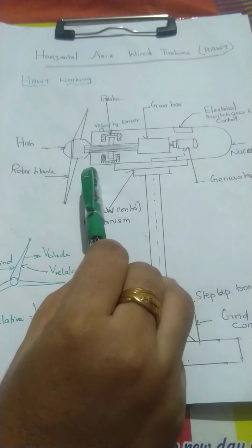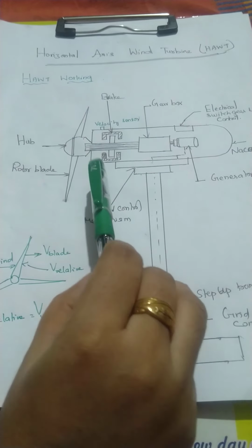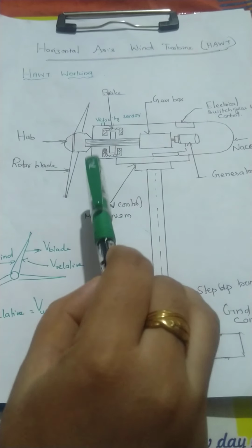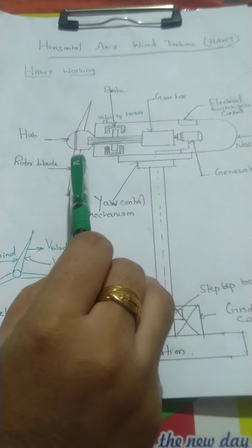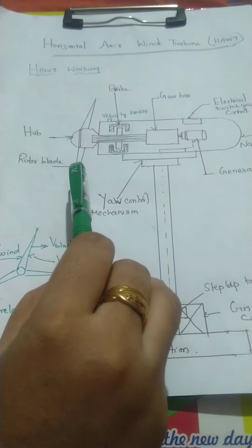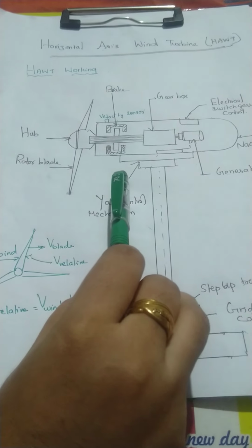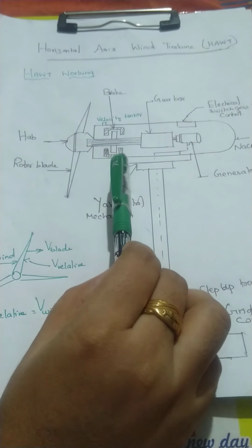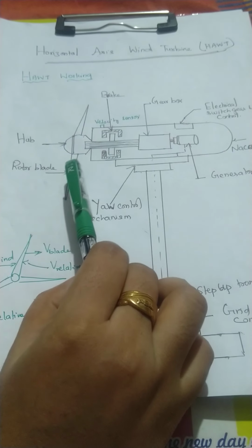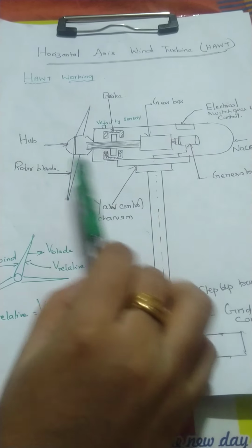According to the wind speed, the relative velocity angle of the wind also changes. A blade tilting mechanism tilts the blades and guarantees a proper alignment of the blade with the relative velocity. Thus, the blades are always at the optimum angle of attack with the relative wind flow.